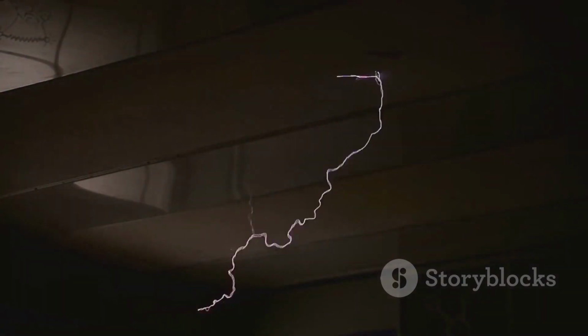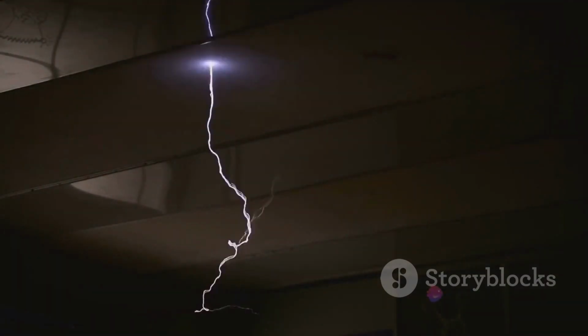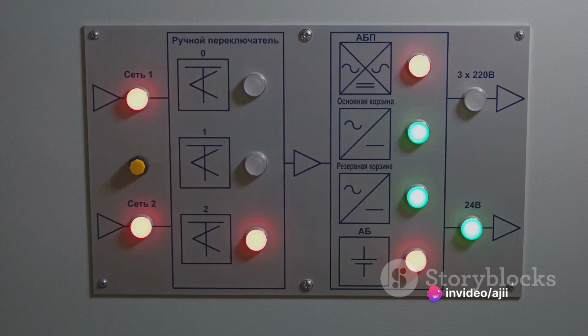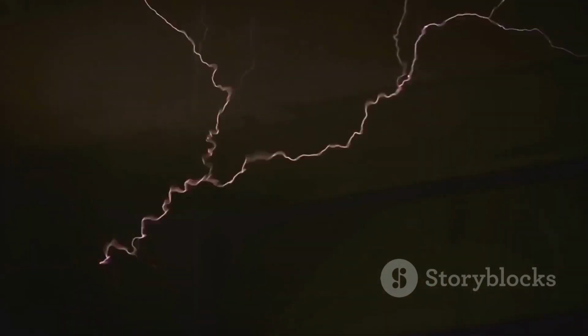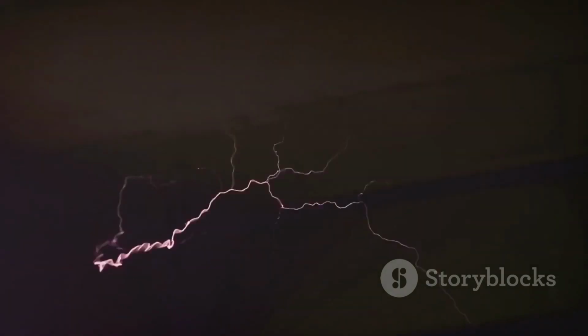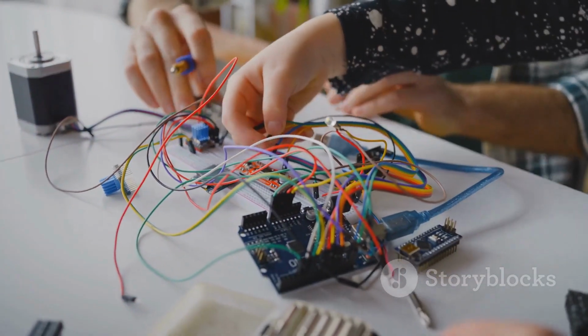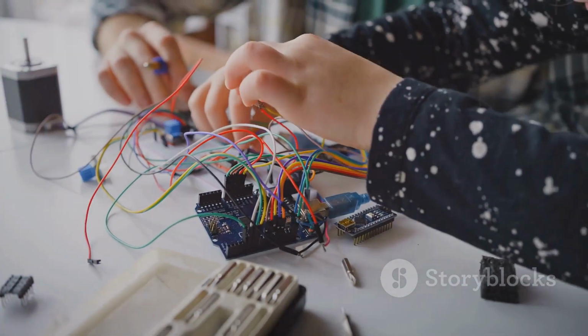When a voltage is applied across a diode, something fascinating happens. The free electrons in the N-type material start to move towards the P-type material. Simultaneously, the holes in the P-type material move towards the N-type material. This movement creates a region along the junction where there are no free carriers, known as the depletion zone. In a scenario where voltage is applied in the reverse direction, the depletion zone acts as a barrier preventing current flow. This is what we refer to as reverse bias.